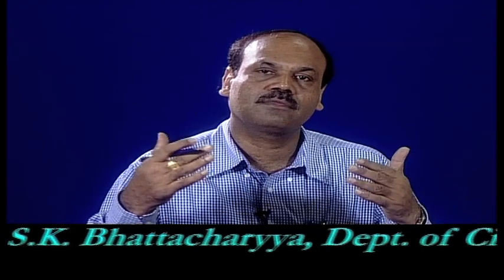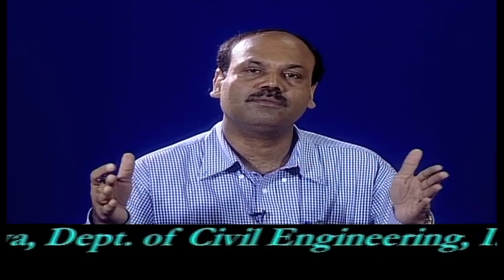Now, if we would like to find out how the shear force is varying along the length, or have the variation of shear force at any point along the length of the beam at a glance, then we need to draw a diagram over the length of the variation of shear force and the bending moment, which we call a shear force and bending moment diagram, which we will look into in this lesson.